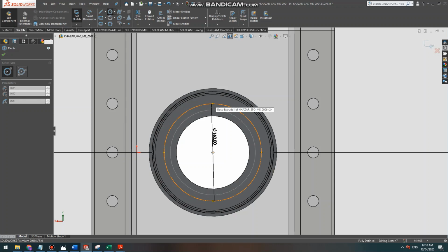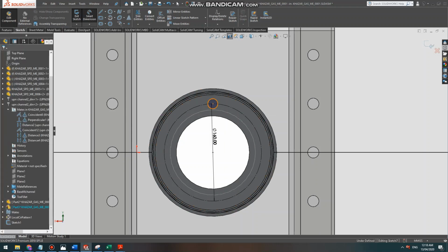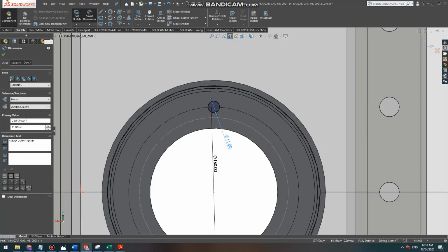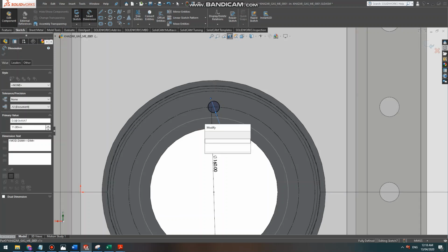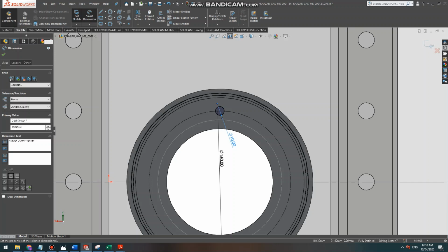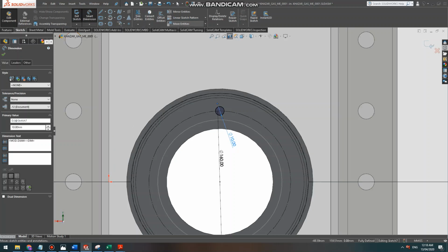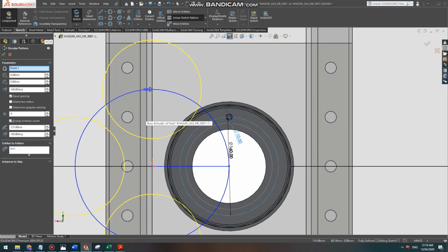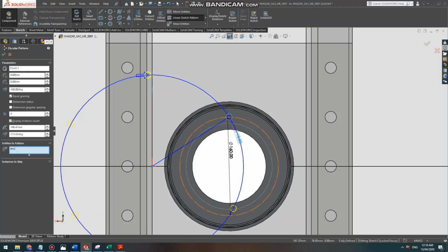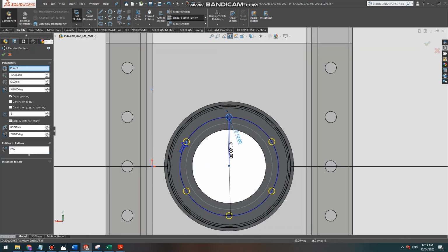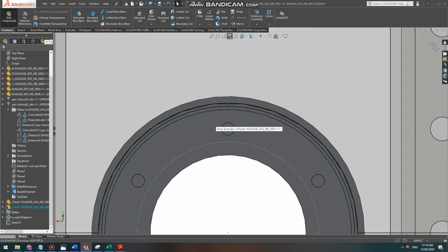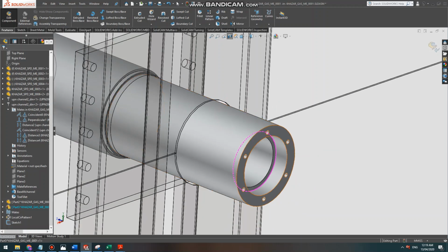We make our holes. There are 6 holes, each of them is 11 millimeters. Yeah, it's 11 for the cap, but for the cap where connected it's 10. It's actually M10. It's the threaded hole where we will place the bolt, and we will have 6 of them in a circular way. We want to do this one around this point, that's it, we extrude it by, let's say, 50 millimeters, and that's the place where you will insert your threaded bolts.